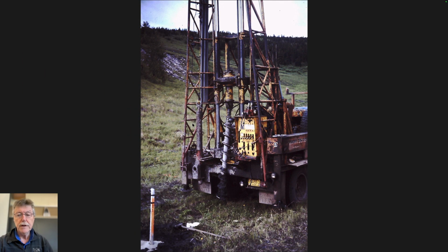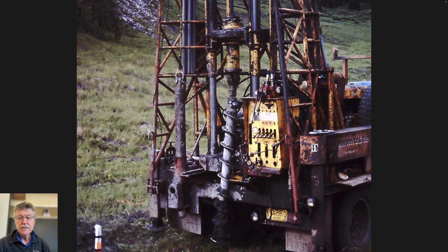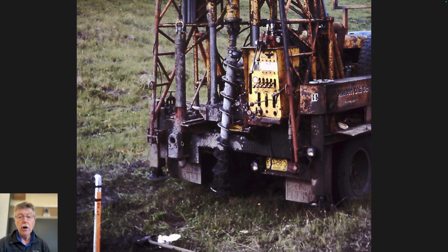We were messing around with some different locations, talked about augers and rotary drilling for soil, rotary drilling and diamond drilling for rock. This is a hollow stem rig with a hollow stem auger with its tip right here and soil on the flights. This rotary connection here lifts the whole material up into the mast.